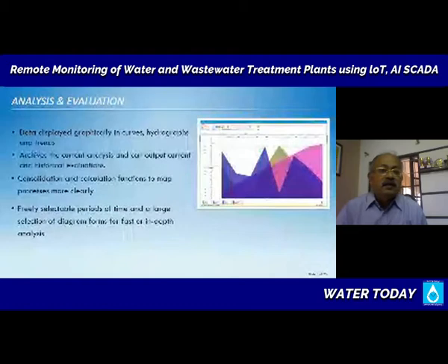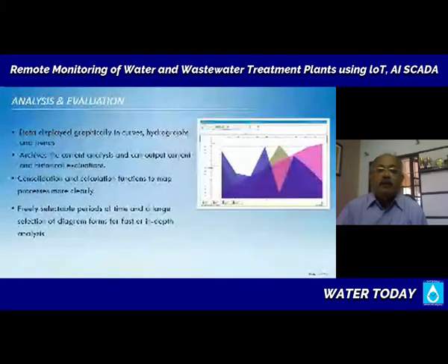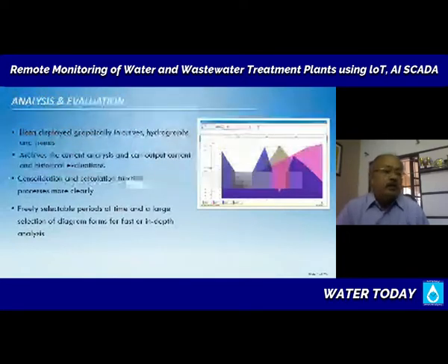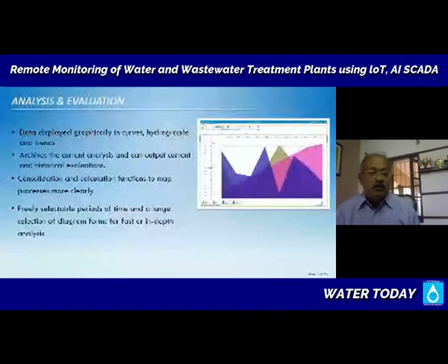And of course, you can analyze the data in graphical ways. This is showing different parameters. A flow that could be going up and down, with diurnal variations and things like that. A pressure drop suddenly in a water network, which is indicating a burst pipe condition. And you can see that all on a timeline: oh, this happened at 9 o'clock in the morning. And you can correlate how this pressure drop also resulted in an increase in velocity. So it helps you to correlate and understand your water network and manage it in a very user-friendly, powerful way. That's what technology allows us to do.